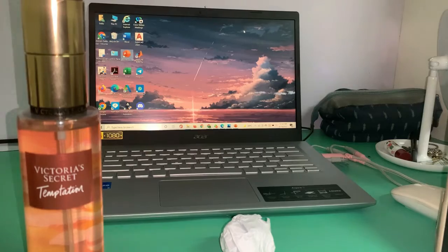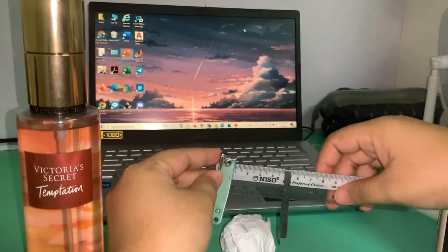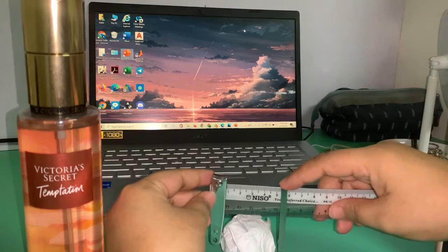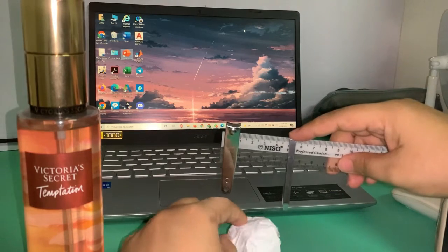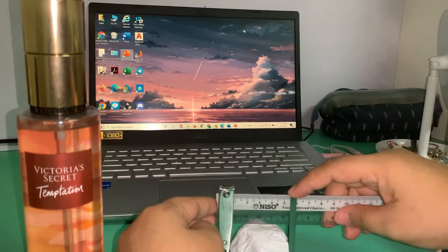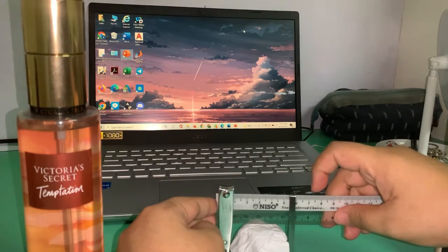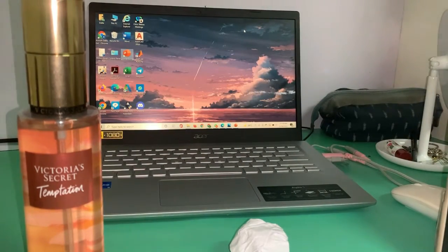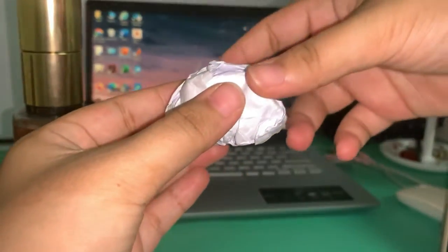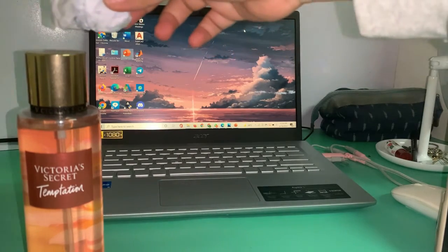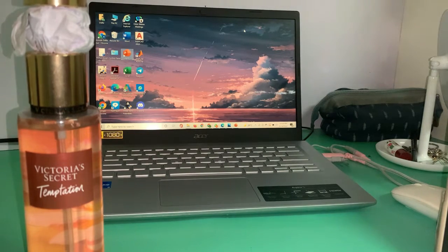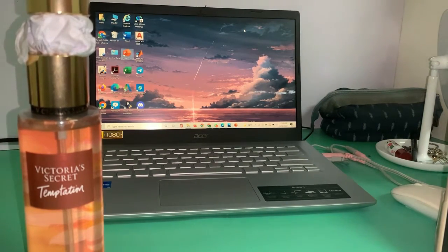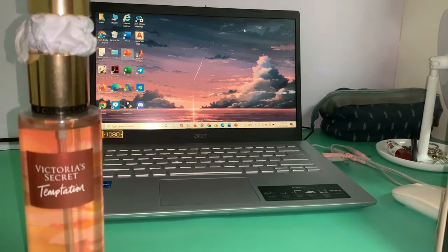Firstly, we will take a sample of rock and then we will measure the dimensions, which are the upper width and the lower width of the sample. Next, we will take the rock sample and put it between the two pointed platens. And then we will apply force, which is load, and when the sample rock breaks, we will take the failure load. That's all for me.